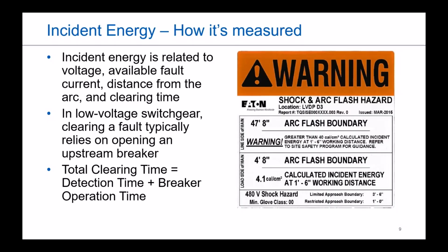But the main things are, what is the rated voltage that you're working with? What's your available fault current? How far are you from where the arc is being initiated? And then what is the clearing time to open and de-energize that circuit?